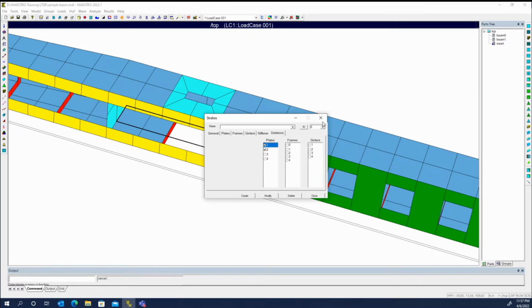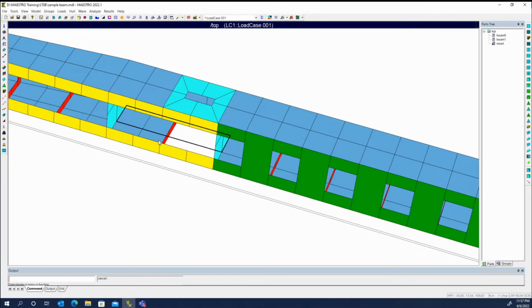We just uncheck those. Also, when you do an operation like that on something in a module, and this applies to the refinement tools and everything, you don't have to make the element that you're going to split or modify with one of these tools the current part first. When you double click on it, the current part will automatically become the module that contains the element you're splitting.